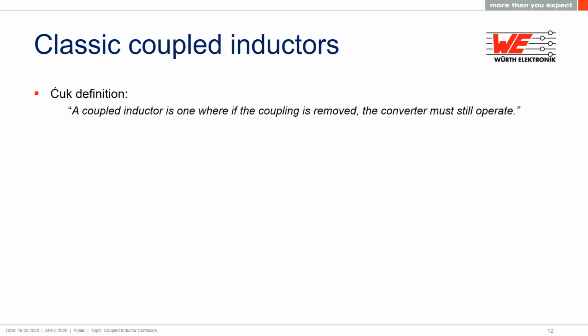I call this classic coupled inductors because it is probably where the term is used the most, in relation to Cuk, SEPIC, or Zeta converters. Professor Cuk defines a coupled inductor this way. A coupled inductor is one where if the coupling is removed, the converter must still operate. What he's really saying is related to the topology, that its function is not dependent upon the interaction of the windings on a coupled inductor, but it can benefit from it. The definition I gave earlier is topology independent and applies to all coupled inductors, of which this is a subset.